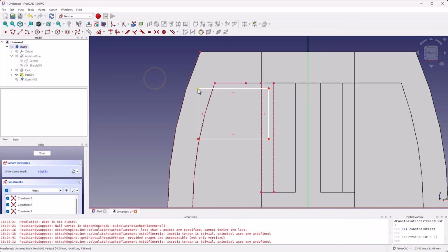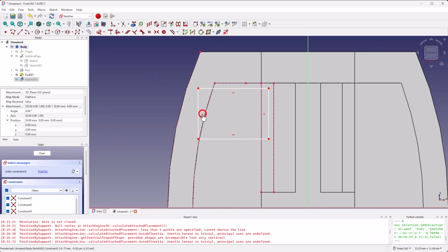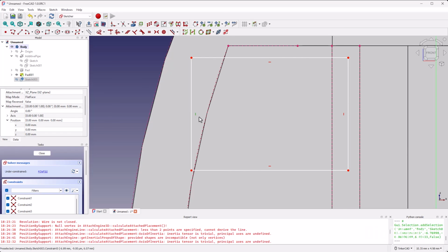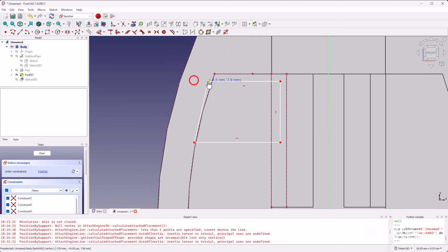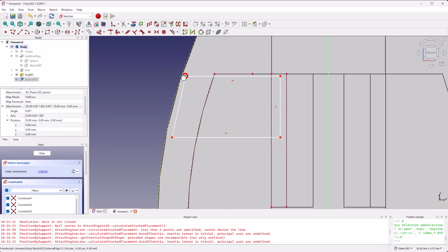Right click. Let's get rid of this vertical constraint. So click on that constraint icon, click delete. Now we can make this like this. This doesn't really need to line up with anything. It just needs to be in there. So we could put it on that line if we really wanted to. In fact, let's do that. Let's attach it to here. Let's attach that to there.